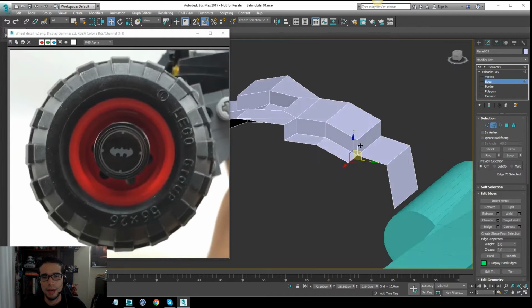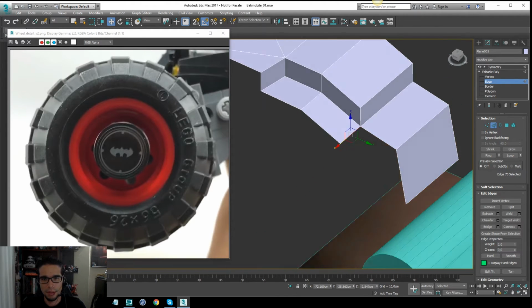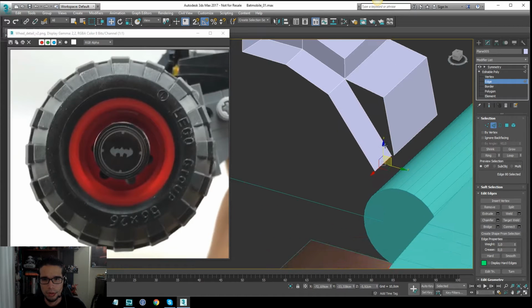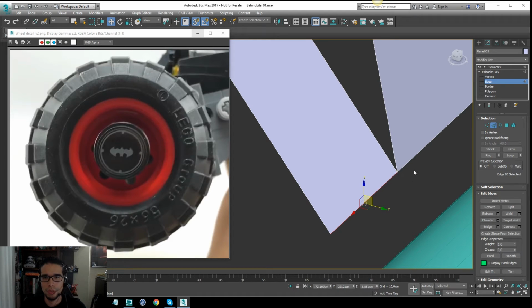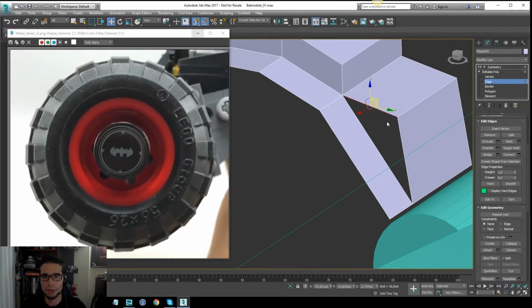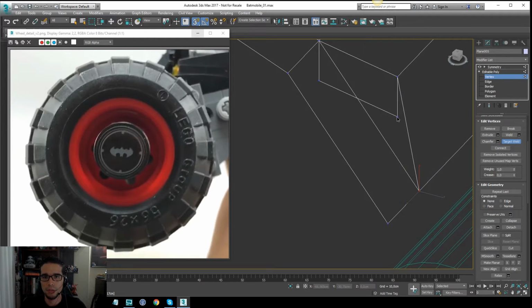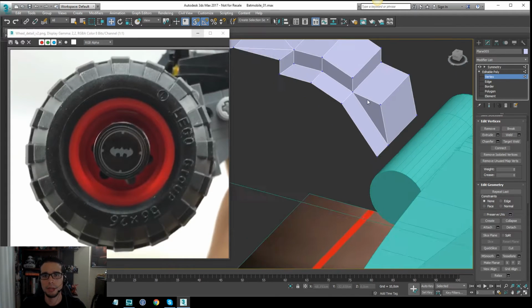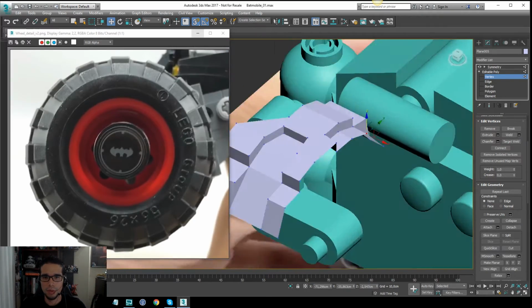Later I think this is going to be exactly the same, as this is a diagonal from one point to the other. So I can use the snap in 3 dimensions, and later I can use the vertex and collapse. Okay, again, to fill this gap, I will shift to create the surface. I will target weld from this point to this one, and remove the other vertex with backspace. Okay, so this is more or less what I needed.